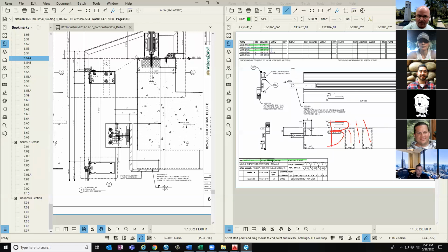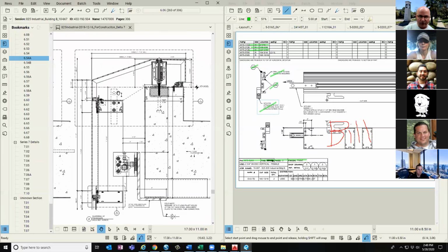Once I've verified all of those, I'll double check the height of this. I'll make sure that my gaskets are showing up properly. Again, I'll see these on my vertical detail. It's showing that I have an access hole required in here. That's so that I have the ability to get the horizontal screws in through this web of the actual mullion. So I'll mark that off. I've got a hook lug and it's showing attached, and I've got a bayonet. So I do have a bayonet showing. I have other conditions on this job where I have a lifting lug instead, so I've got to look for that on those other types of units.